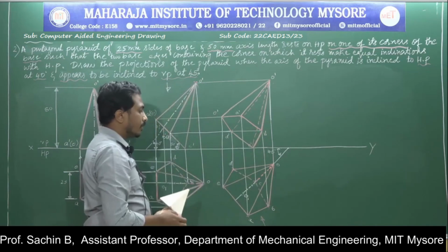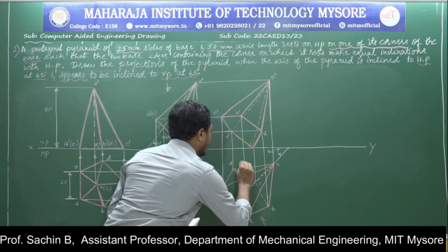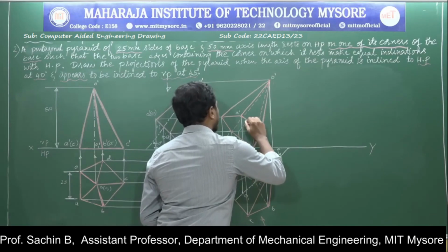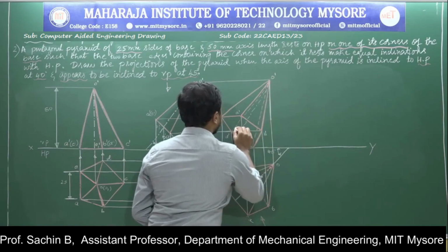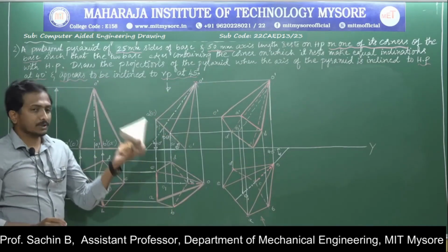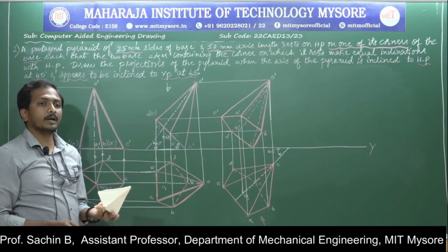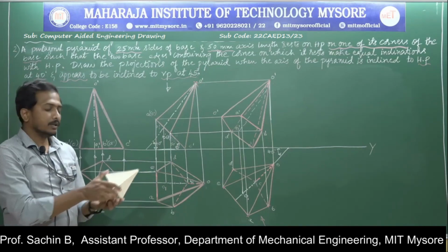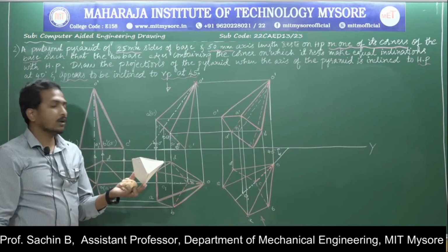This is the final appearance of the object, and one more thing we have left, that is nothing but to draw the axis. I am drawing the projection line to the top. Again from here I am drawing the chain line to get connected to the axis. This is my O1 dash point. Now in this problem, it is purely an axis condition problem, but here it appears to be inclined. In the sentence they have given, there is no need of finding out the beta angle. They have clearly given the last position inclination of the pyramid with reference to the vertical plane.